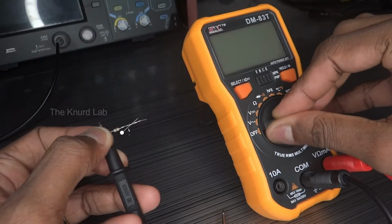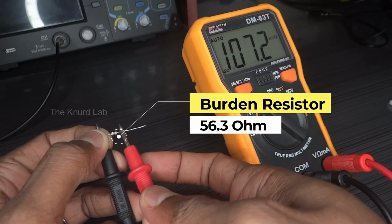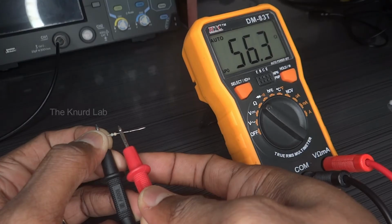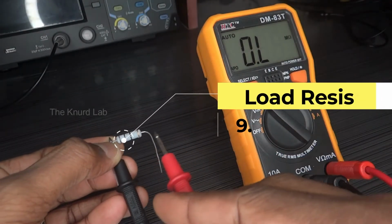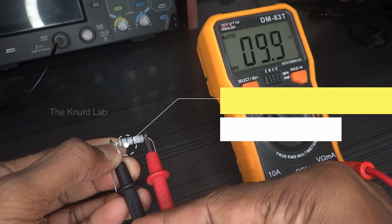The resistors used here have 5% tolerance, so it's important to measure the actual value to reliably calculate the turns ratio. For this step, the value of the burden resistor is not critical. You can use any value between 50 and 100 ohm and make a decent measurement.